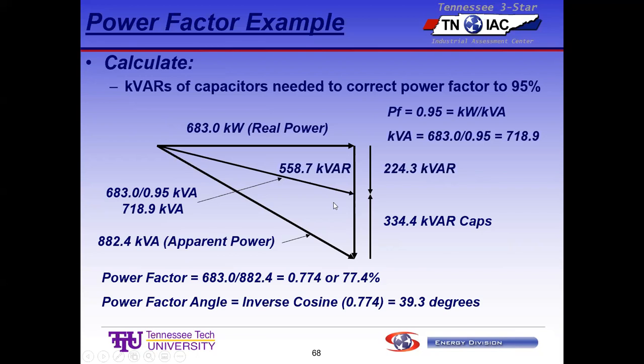Well, what you can do is go out and measure with a good power meter. You can measure the power factor. You just clip it on each motor, and you go, oh man, this motor is running 75% power factor. This motor is running 60% power factor. This motor is running this. So you can go to the individual motors and put capacitors on.